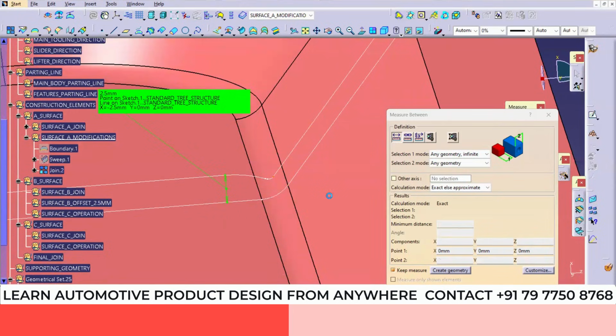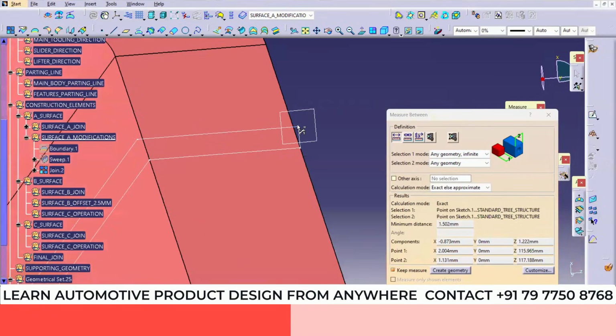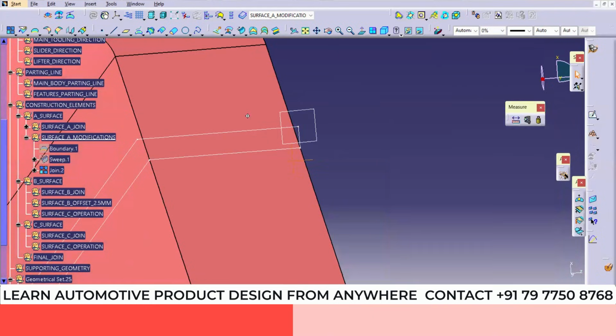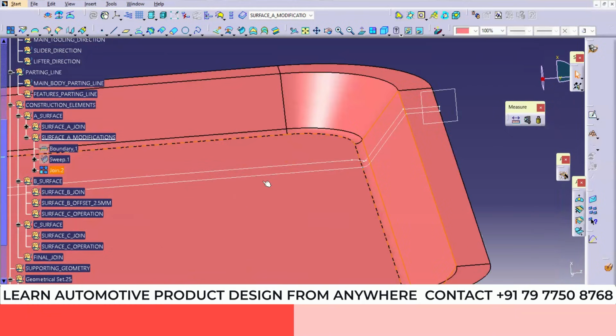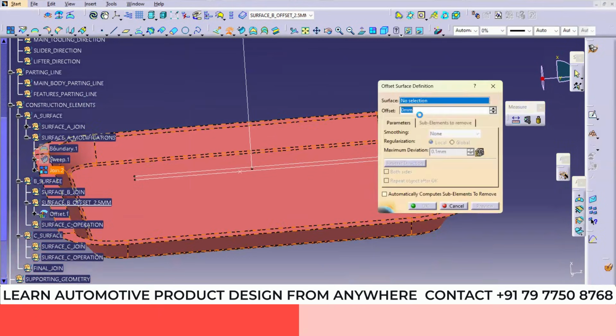This to this is a different value, right? This is 1.5, and here also 1.5. So this 1.5, this 1.5, and this is 2.5. Different thicknesses are required, right? So for the B surface, we'll go to the offset of 2.5, and first I'll offset by 2.5.